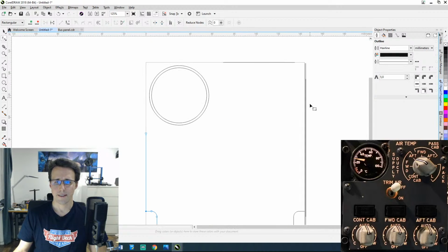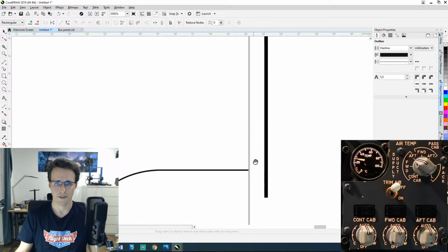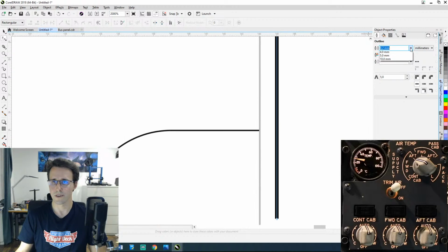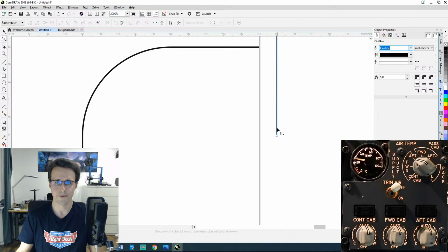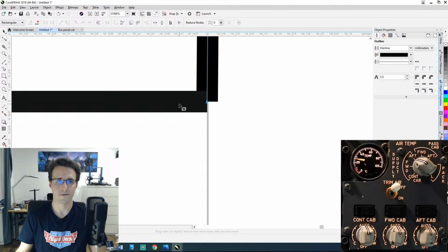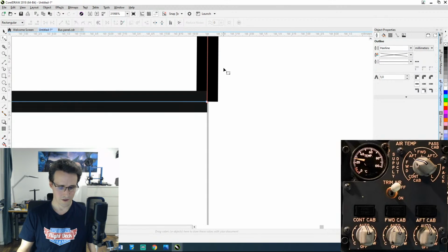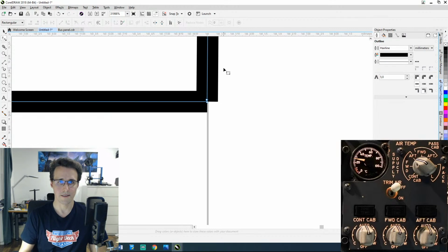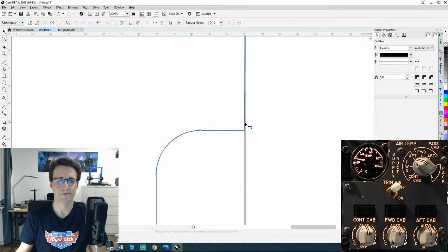So let's connect these here. This should be a hairline. And then connect it here to this node. Or maybe we... What's the shortcut? Who remembers? Control L. They are combined now, and now they are connected.